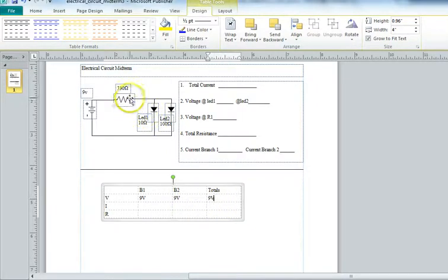And that means that it doesn't matter where you're measuring. If you wanted to simulate this, you could do it on the circuit simulator, and you'd find 9 volts anywhere you measured across these or across those. And you'd have to do that with a voltmeter. We don't know the currents yet, so we've got to calculate the currents, and we'll do that later. But we do know that this branch right here has a certain amount of resistance in the branch. And so if you add this resistance and that resistance, you'll get the resistance for that branch. You'll get 340